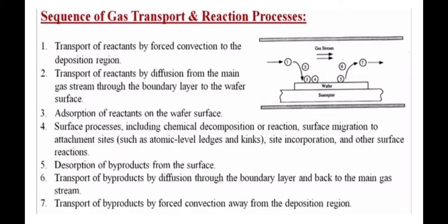So initially I have one chamber in which I put my substrate, known as the wafer. Then I inject the reactive gases. But the problem is that the reactive gases may not come into direct contact with the surface of the wafer. That is why we use a certain kind of force gases, generally called carrier gases, which take those reactive gases with them. The role of the carrier gas is just to carry those reactive gases inside the chamber and take them out of the chamber itself.